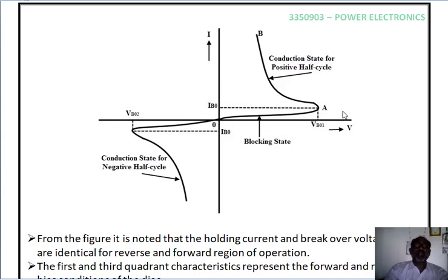During this period the diode acts as an open circuit. The diode is designed for a breakdown voltage of 30 to 35 volts in both directions. That means it requires 30 to 35 volts to turn on the diode in both directions.